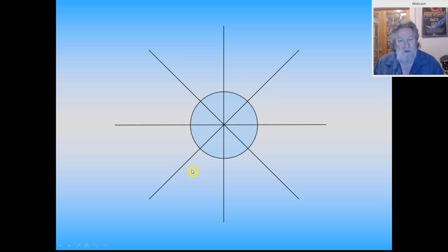We began with cross axes, an X and a Y axis, and two at 45-degree diagonals to the principal ones. That divides our circle into 8 equal parts, which would be the basis for the construction of an octagon. But we're not going to go into that with this particular lesson.